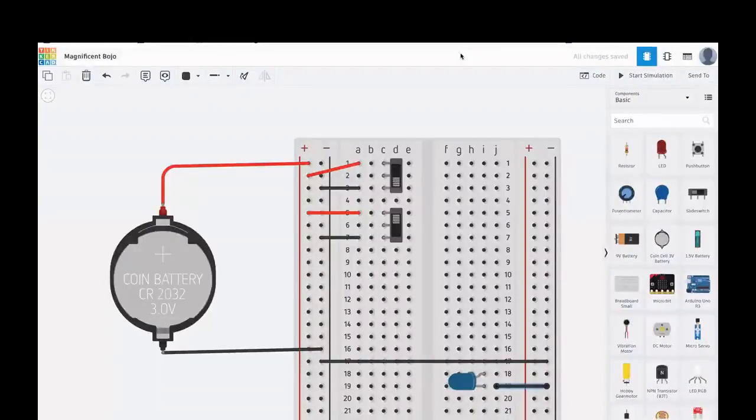All right, in this next example, we're going to look at gates, so we can see how we use logic gates. To start setting up these logic gates, I'm going to have two inputs to the gate. So I have two switches, one for input 1 and one for input 2. And then the output will have this blue LED show the output.